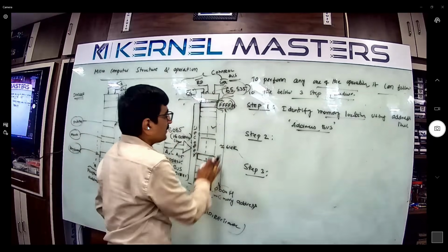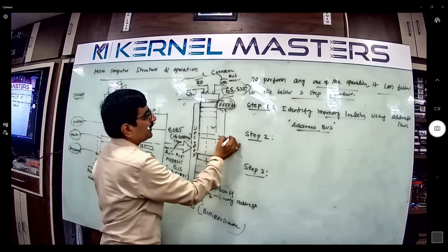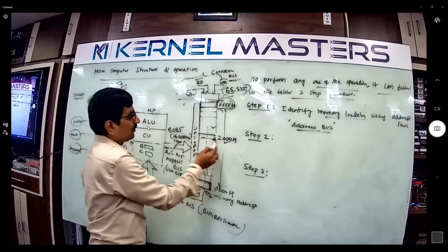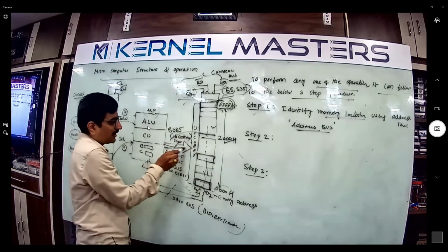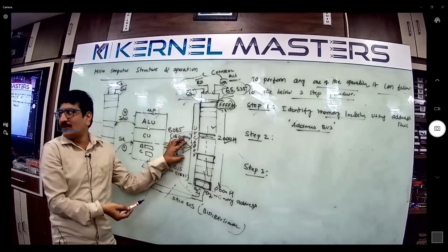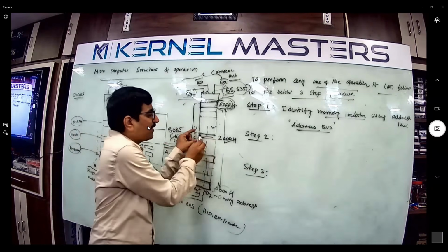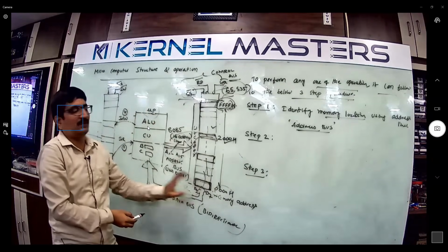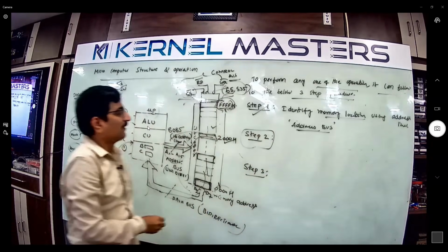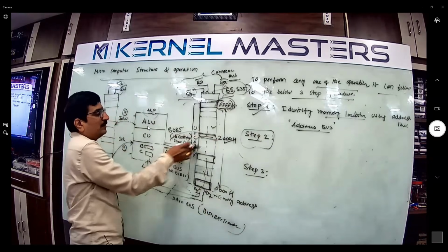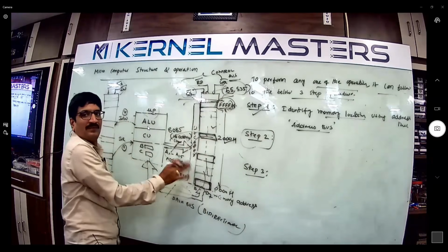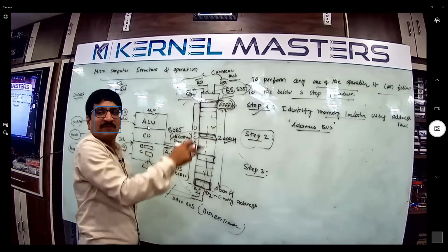For example, assume the address is 2000H in hexadecimal. The microprocessor wants to read from location 2000. The address decoder decodes the input 2000, selecting the 2000 location, and the remaining locations are disabled. Once the address is selected through the decoder, all the remaining outputs are disabled. Through the address bus, we select this address and the rest are disabled.